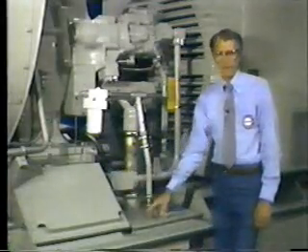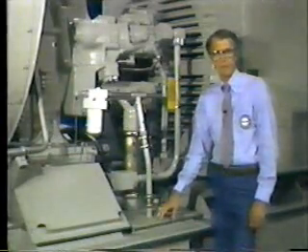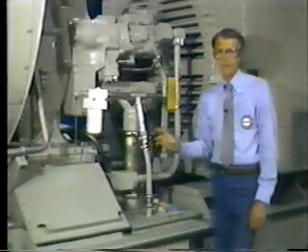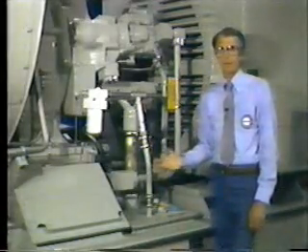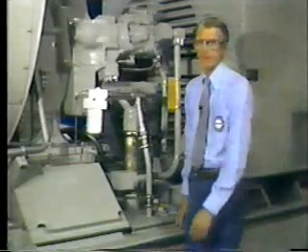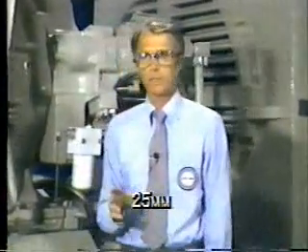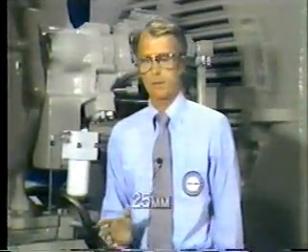Oil tank air pressure is very important for the effective operation of the seals. If the tank vent is not sized properly or is restricted when installed, a back pressure will develop in the oil tank, reducing the effectiveness of the seals. Normal oil tank pressure should be less than 25 millimeters on a water gauge. Oil tank pressure should be measured and recorded when your engine is new. Subsequent readings can be compared with the initial reading for an evaluation of engine seal problems.